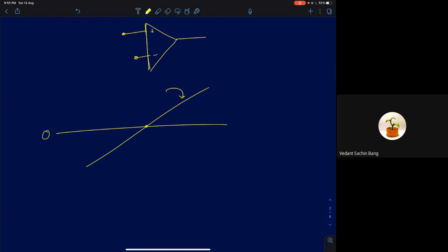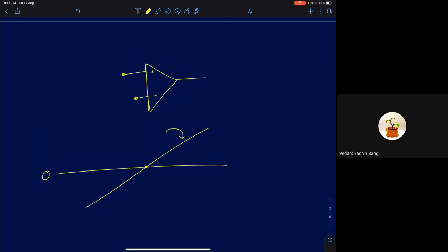Most analog circuits come with noise. I haven't yet discussed in any lecture how to characterize noise, but for the time being, I'll very briefly discuss for a minute how to characterize noise. A noise is a random signal. So you don't know what exact value the noise will take at any given time, but you can tell the statistics. If you study the values it's taking and try to fit a probability density function, typically they turn out to be Gaussian in nature. Most noises are called white noises and Gaussian white noises.